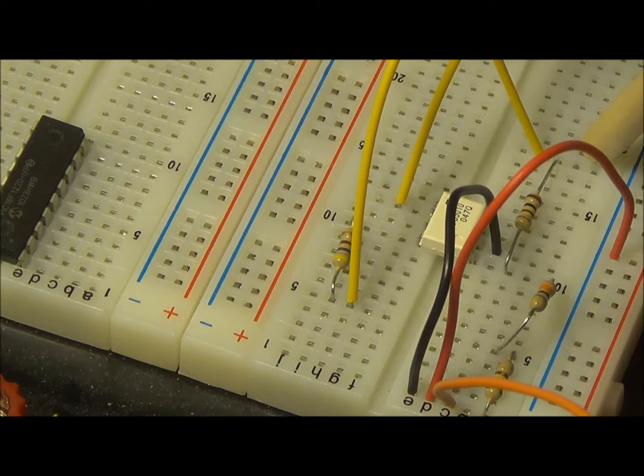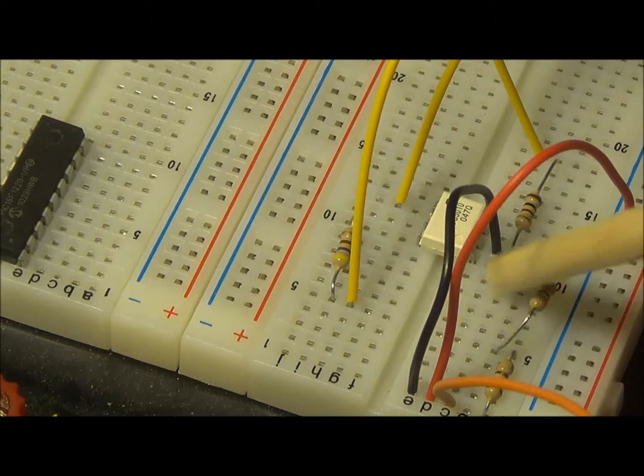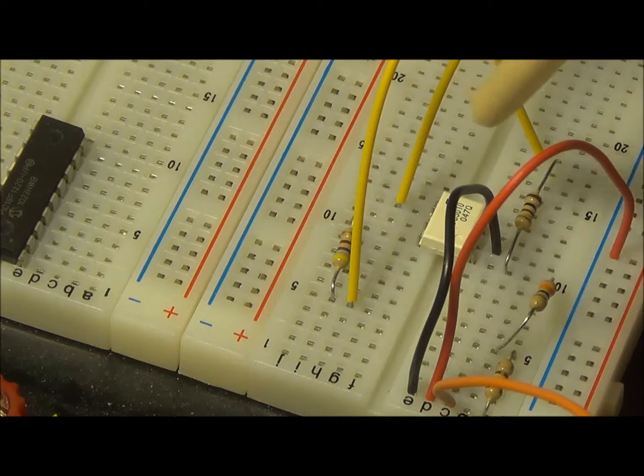It delivers 3.2 volts. However, the 3010 optocoupler chip can take only 1.2 volts, so I had to reduce the voltage using a voltage divider. So 1.2 volts goes into the input, and when it receives that voltage, the output goes into conduction, and then that triggers the diac, and as a result, the triac gate gets triggered and the current starts flowing to the AC load.